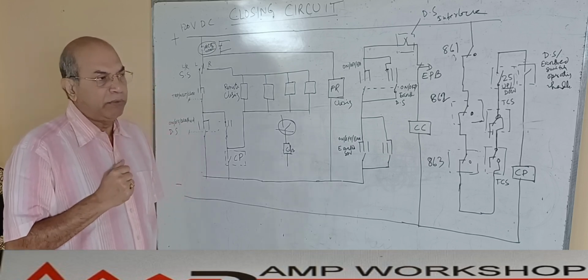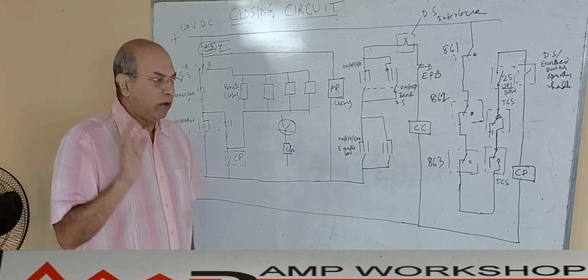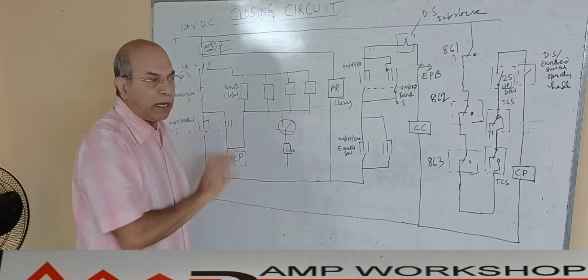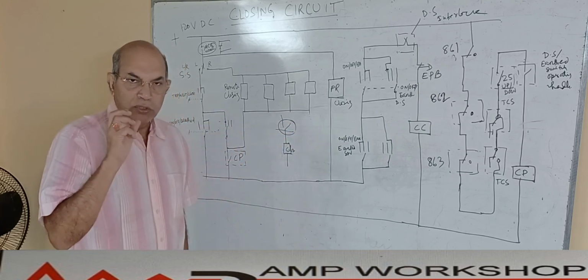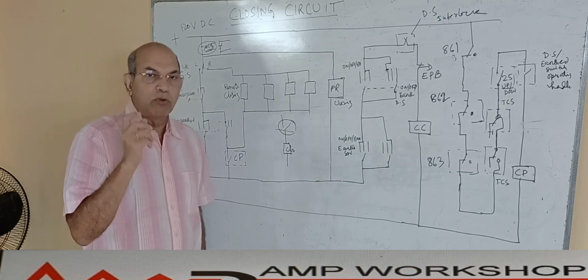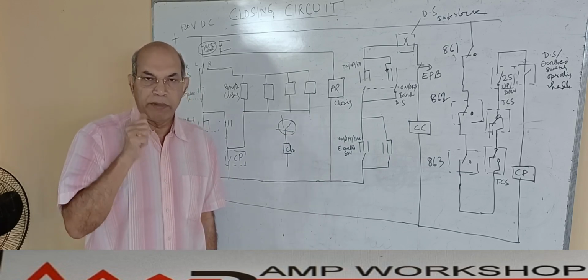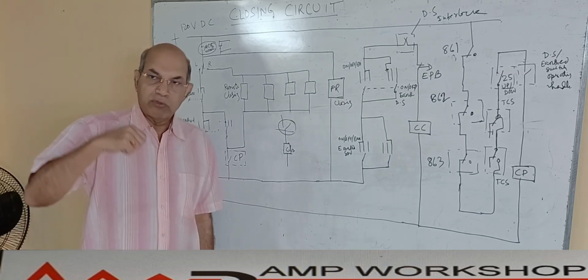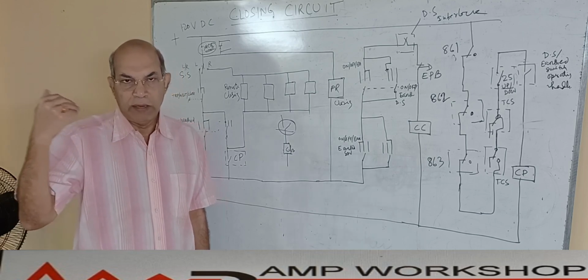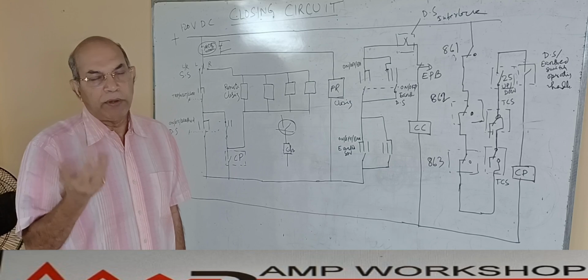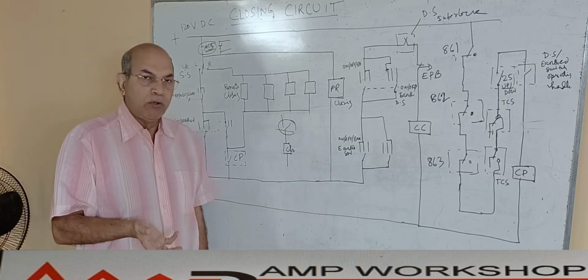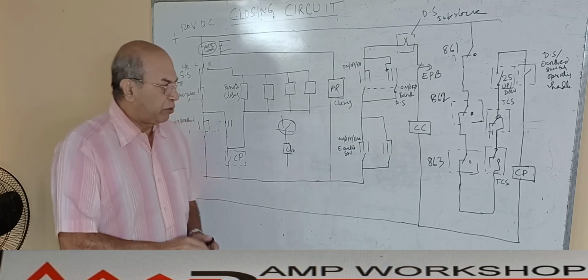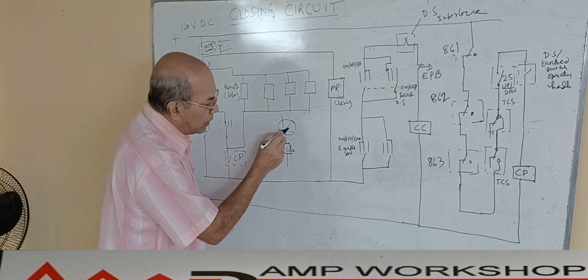During testing of the circuit breaker, we keep the power circuit off. How can we do the power circuit off? We switch off the isolator, so the power is not coming, and then we go to the closing. We test the closing circuit or closing coil of the breaker, whether the breaker is getting closed or not. That is one occasion. Another occasion, due to some remote problem, maybe the breaker is not able to close from the remote, and during operation we need to close the breaker. In that case, we will come to the local panel and we will close the breaker. In that case, the breaker will be in service position, means the isolator is closed.